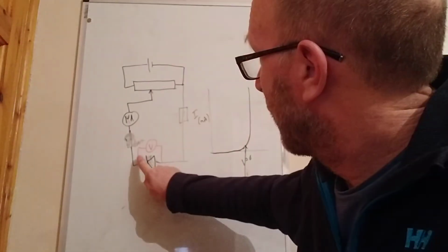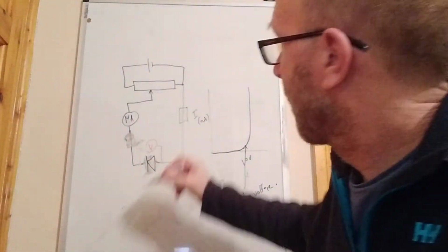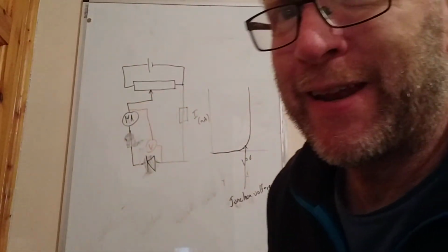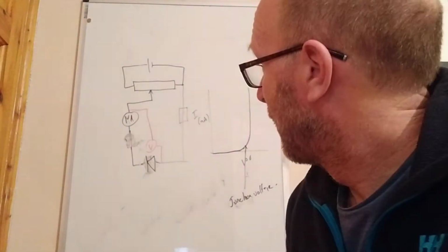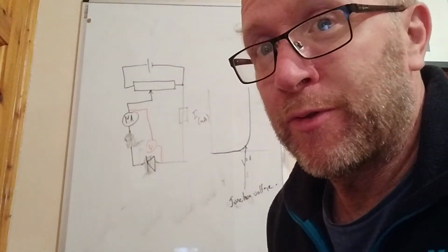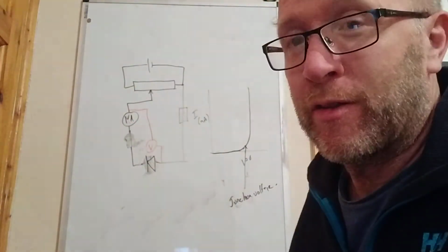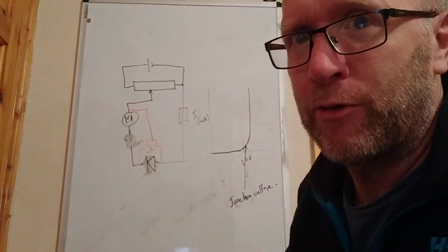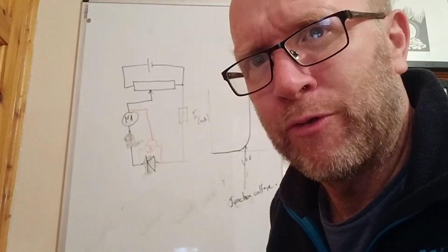So what we do is, watch, we put the voltmeter across the microammeter and the diode. The microammeter and the diode, okay? Now, what difference does this make? Well, first of all, it makes the reading of the current perfect, because the current flowing through the ammeter is now exactly the same as the current going through the diode. The question is, have you compromised that with the voltage reading?